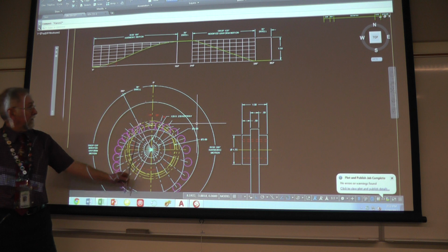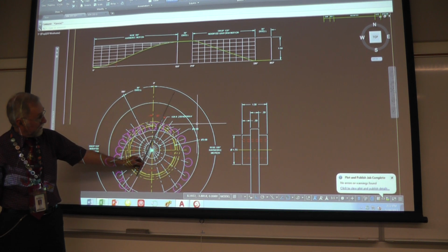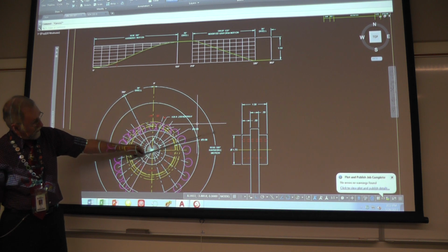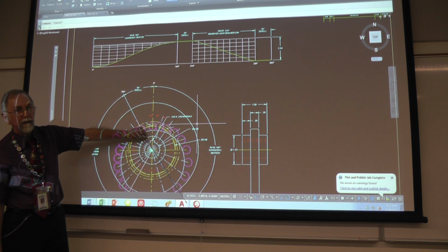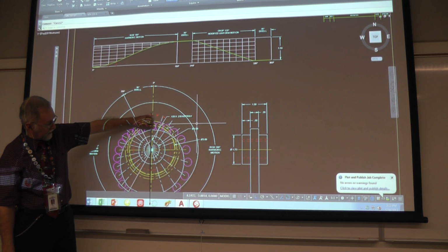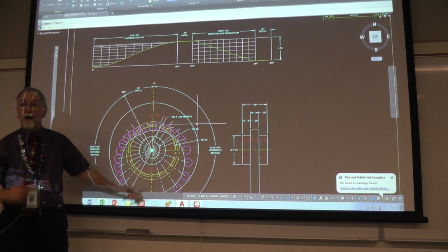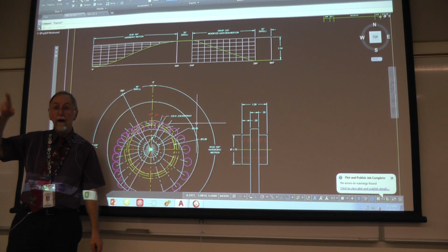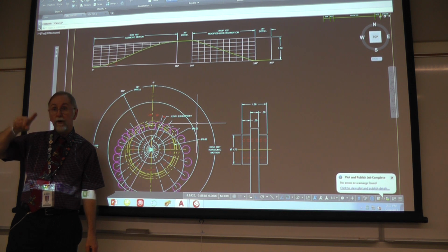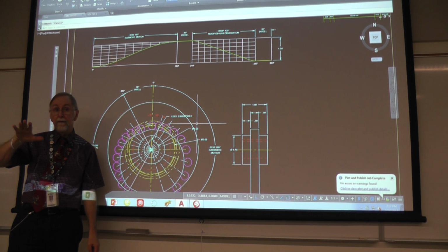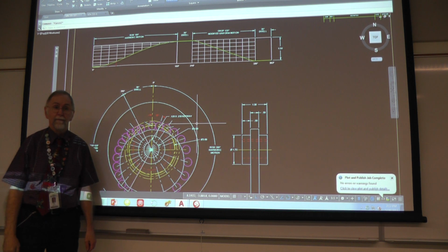All right, I've got a center line here. If you do an array, and array this 18 degrees between these objects, if the array pattern has 11 objects in it and it arrays 180 degrees, you'll get 18-degree increments as center lines that radiate out from the center of the shaft. Questions on that? Okay. So you're saying 11, which will give us 10 spaces, 10 lines. Okay. Yeah. That's how it works.